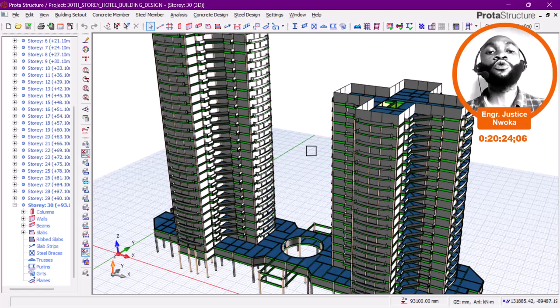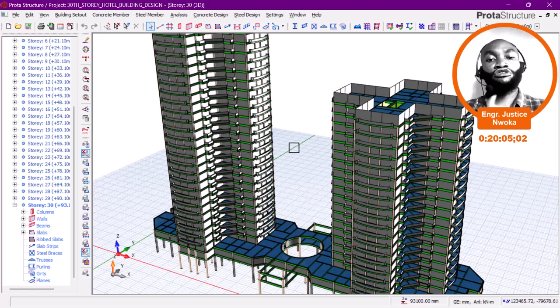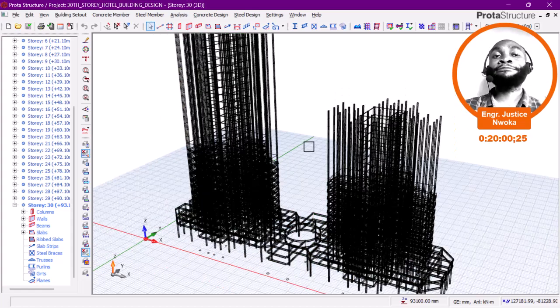But when it comes to seismic joints, the width goes all the way to 200 millimeters. So you can see that it is quite different from an expansion joint, and the way you design or treat a seismic joint during the construction stage is different from the way you treat an expansion joint.